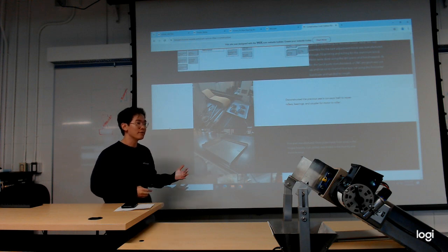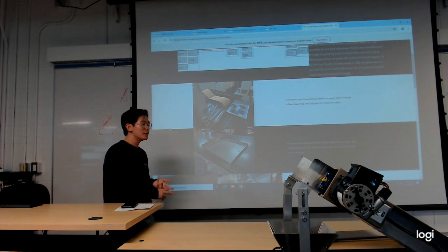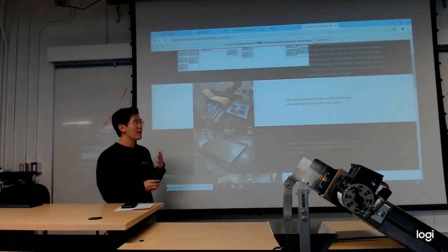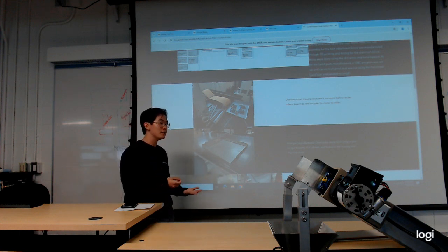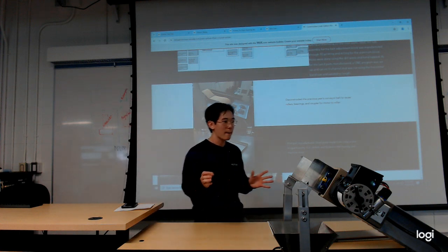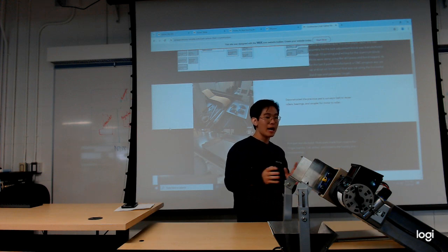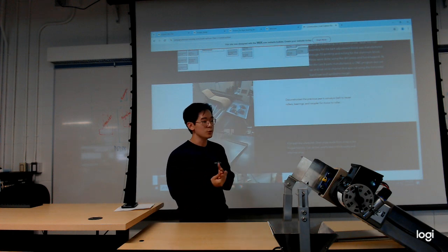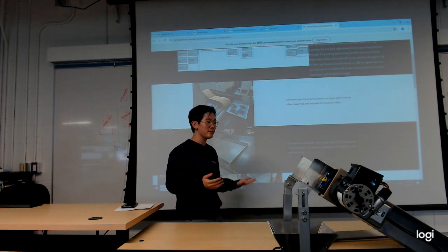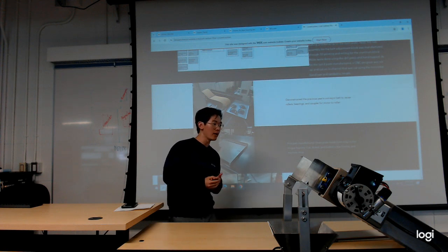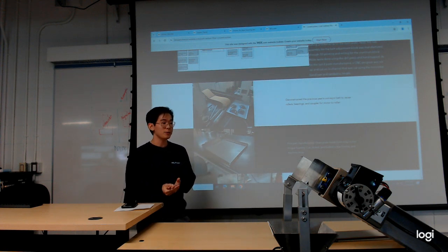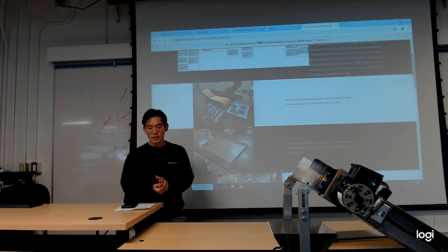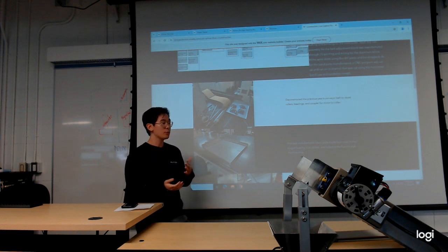I wanted to do a lot of different things such as folding sheet metal and welding, and after some design changes, I understood that a lot of those things weren't entirely feasible, so I made changes such as changing my frame here to aluminum rather than steel. I pre-purchased pre-cut material for the U-channel, and I used a CNC machine to drill everything out, to make sure it was very even and very, very precise. A lot of the other things I ended up using were 3D printers, milling, drilling, and just doing it all by hand. A lot of these parts were pretty simple, so they were pretty easy to make.